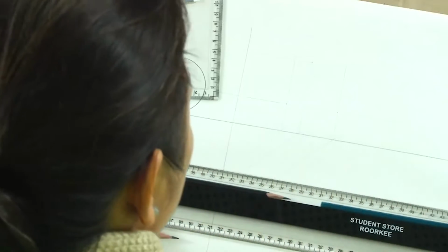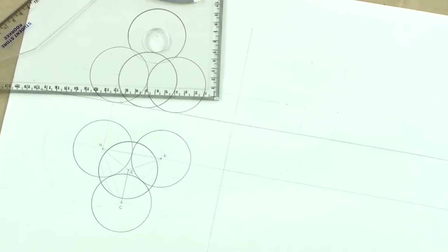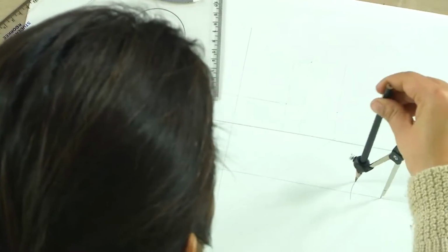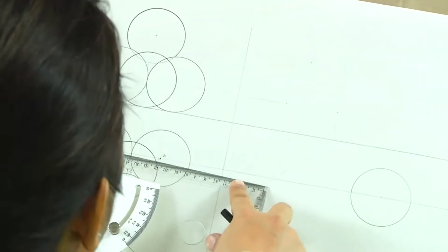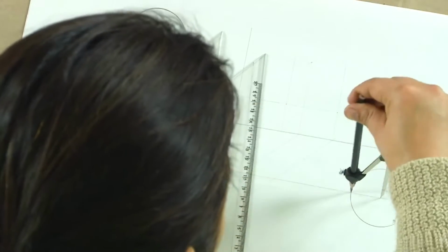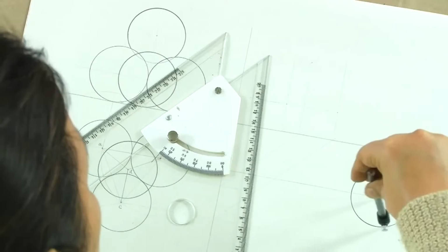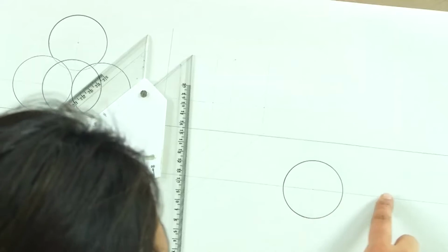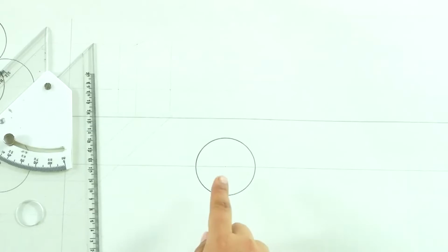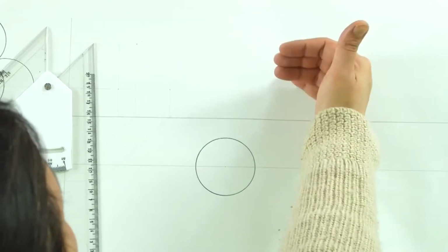Now, let us take an example where there are two unequal spheres. So, let us have the first sphere as the small sphere, having a radius of 2 centimeters. So, that is the smaller sphere. Now, we have a bigger sphere which is kept in the same line as this. The line which is connecting these two spheres is actually parallel to VP, but it will not remain parallel to HP, because the center of the bigger sphere will lie slightly higher.